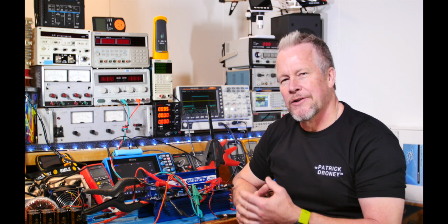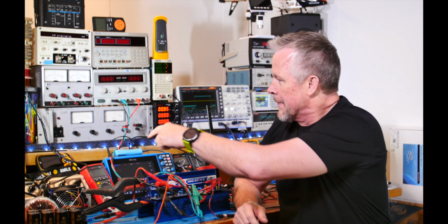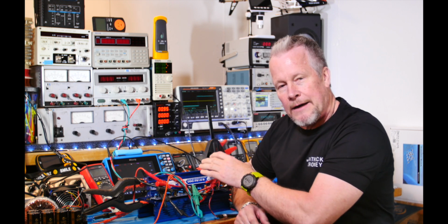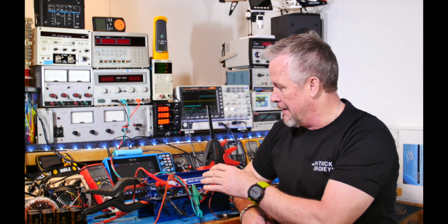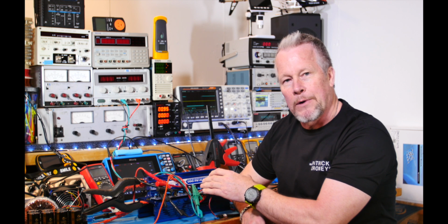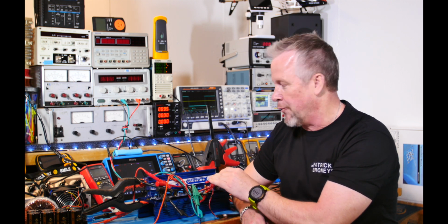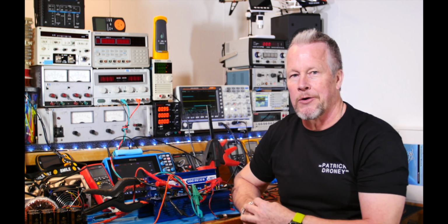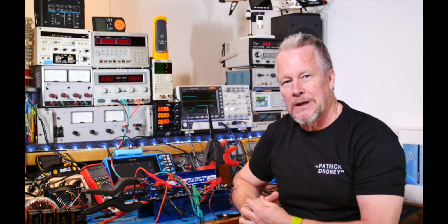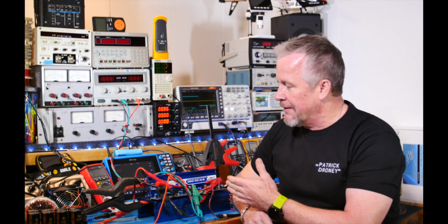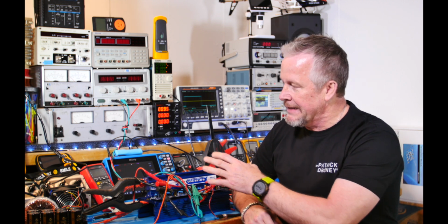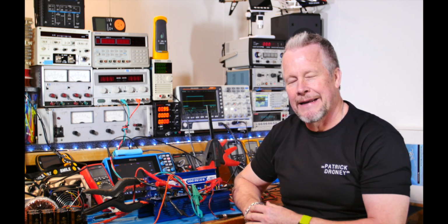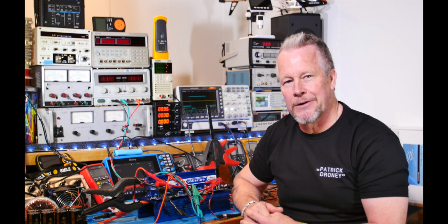One thing I thought about after the video is that this amplifier board has a setup where you set 4.5 volts across this current source so you have the right amount of current. It sets up your bias for the Class A. I set it up for 4.5 volts, but then I didn't notice that it dropped, and it didn't really register until after the test.